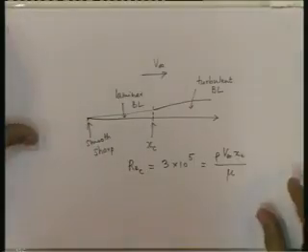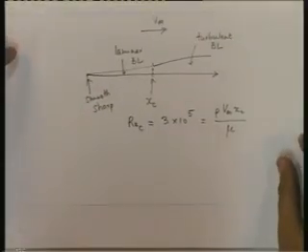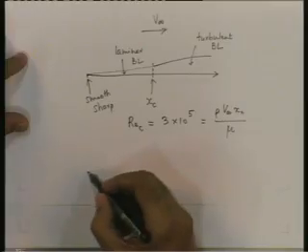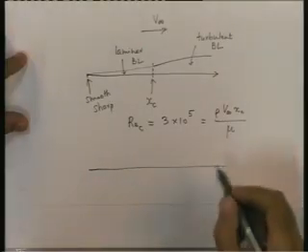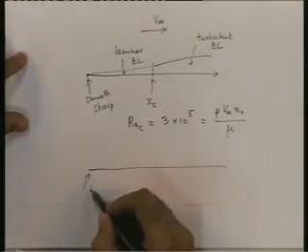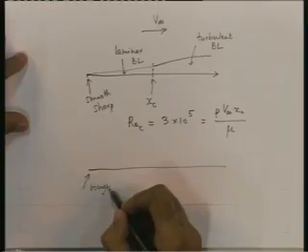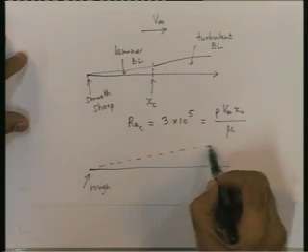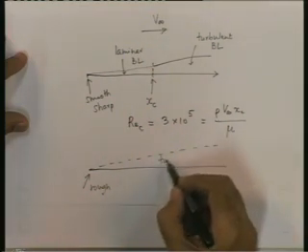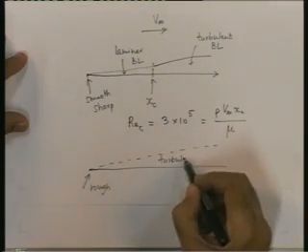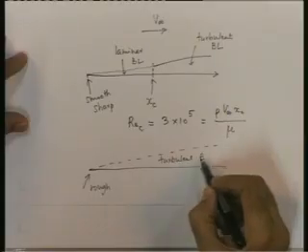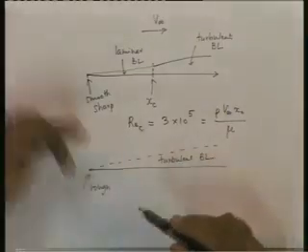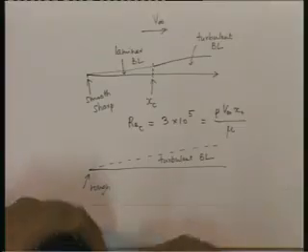If you make the leading edge rough, ragged, then it is possible to have a turbulent boundary layer right from the leading edge. That is the difference between the tube situation and the boundary layer situation.